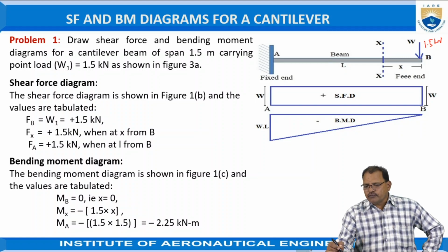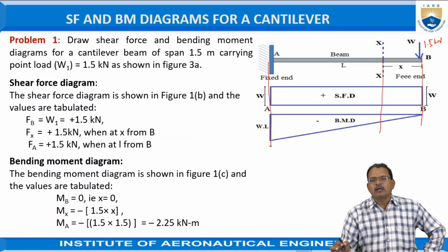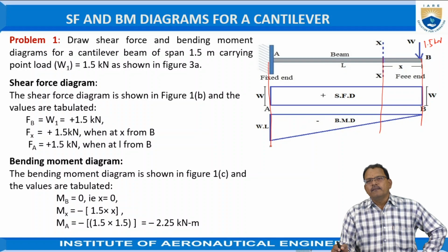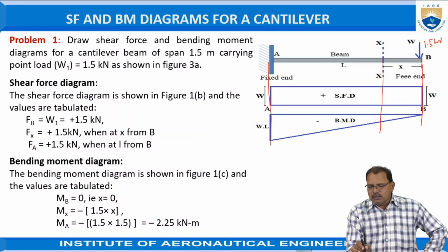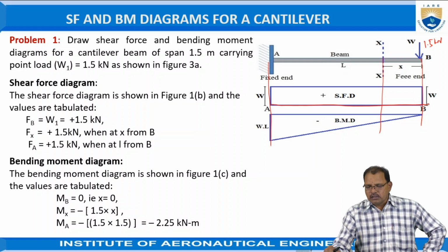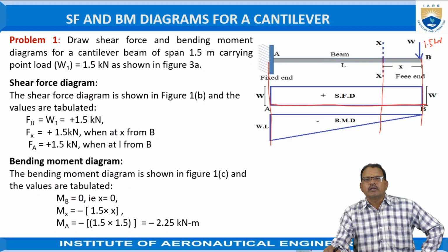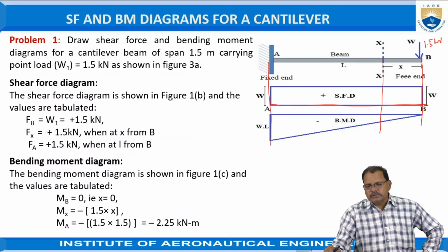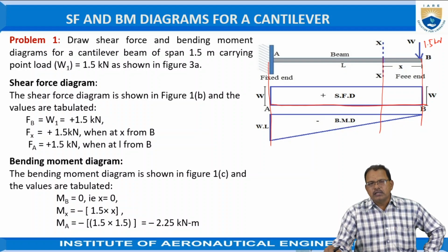So in order to draw the shear force and bending moment diagram, first of all draw the vertical lines passing through the sections of the given beam. Now draw horizontal lines. Since the shear force is positive for the cantilever beam, because all the forces acting according to that figure are in the downward direction with respect to the left-hand side, they are considered as positive forces.